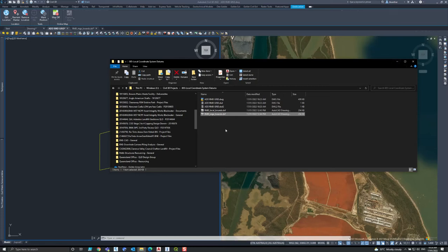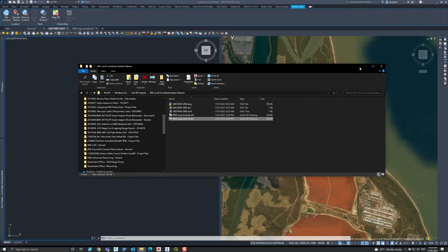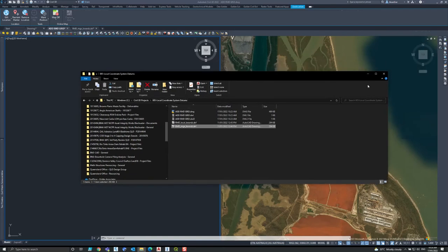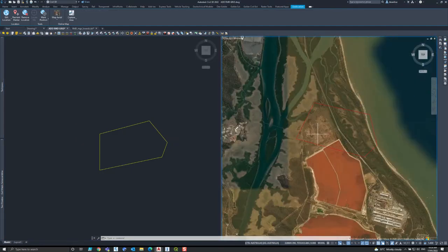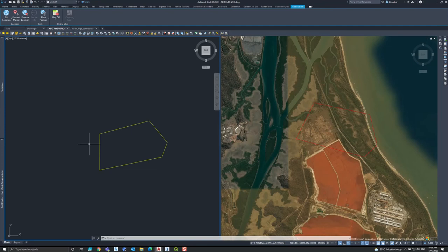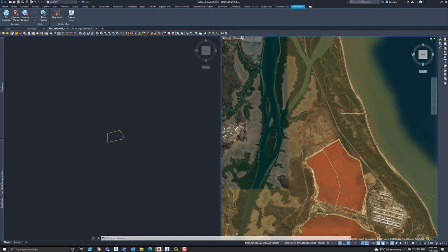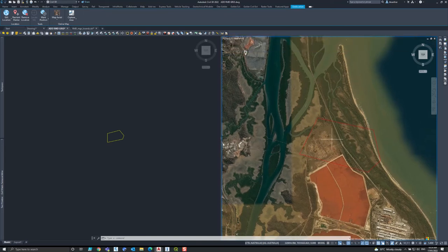And we can use this in GIS programs, and we can also use it in CAD and all the other CAD products like Infraworks and other environments that support coordinate systems. So it flows through to the whole ecosystem. Let's say we've got this boundary, given to us for some sort of lease boundary, and we've received it in both the local coordinate system, so that's why there's no imagery here, and in the known coordinate system, which is MGA Zone 56, 1994.